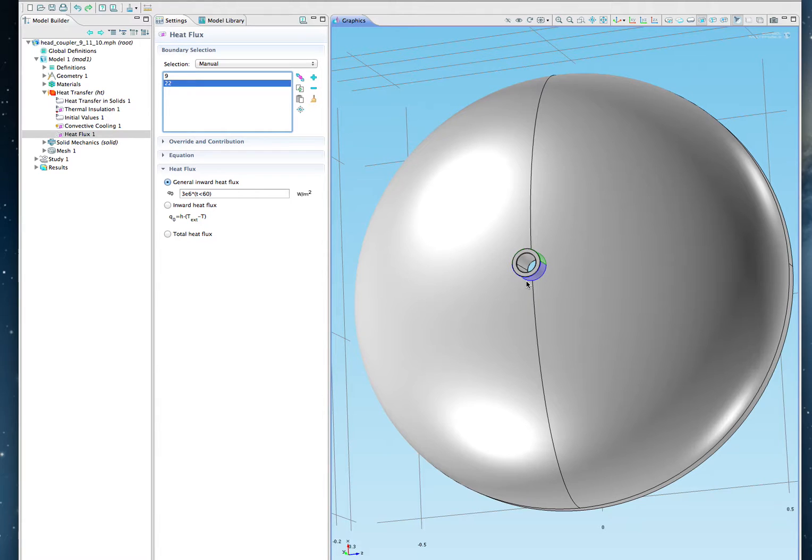I could have programmed it to start from here and give it an angle and then rotate the torch, if there's a torch that is heat flux, and calculate some time dependence of that and put it in here. But I opted not to do that because they go very fast, and therefore within a few seconds you have the welding, and then you turn it off.